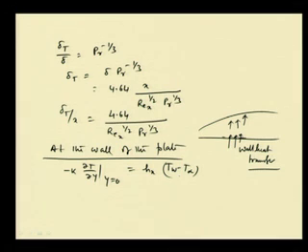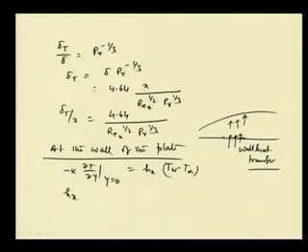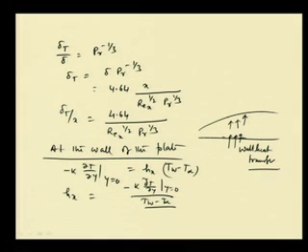So, Fourier's law, which is the conduction mode of heat transport at the wall, becomes Newton's law of cooling, which is the convective mode of transport, and in both cases the area remains the same. That is applied under steady state condition: whatever is coming in is getting convected away. So, under steady state condition, this is the balance equation, and h x is equal to minus k del T by del y at y equal to 0 divided by T w minus T infinity. This is what h is.